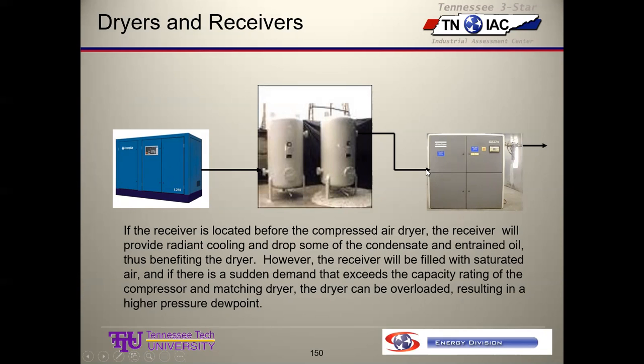The benefit to this is that the air spends some time, depending on how big the tank is, flowing through the tanks, out of the tanks, into the dryer, and out to the system. So it has some residence time in these tanks. It can lose heat, because coming out of the compressor package we're probably 95 to 100 degrees at least. If we lose heat in these tanks, then we drop some moisture.